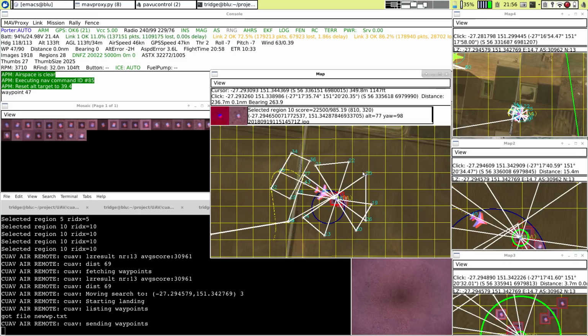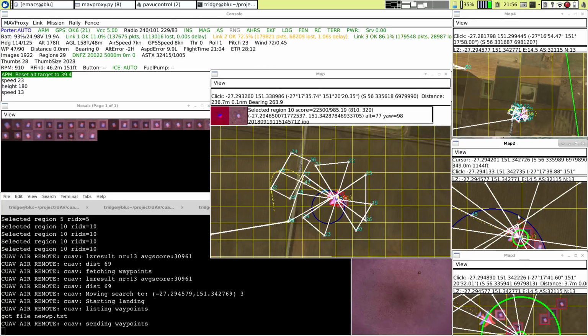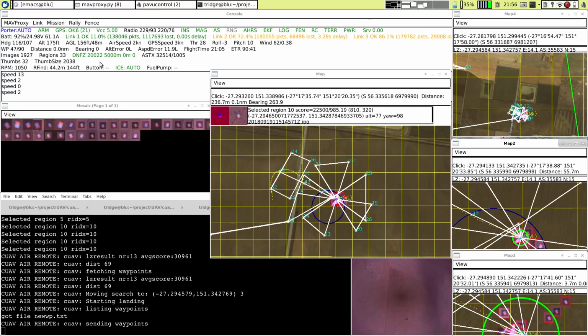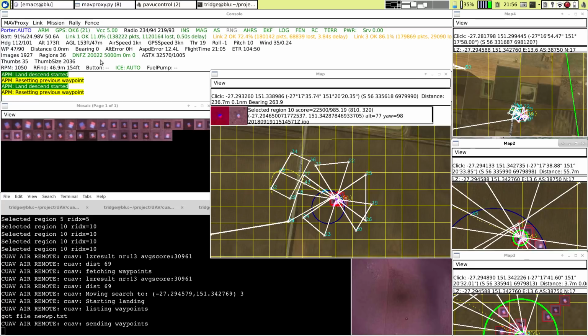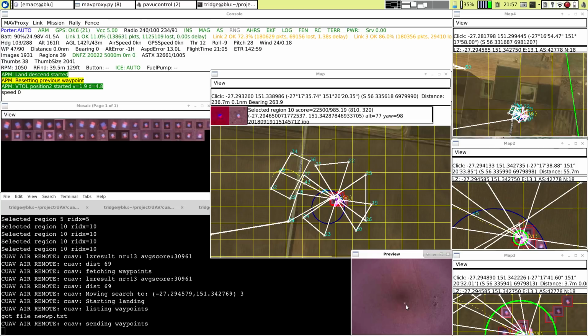So there it is, and you can now see it appearing on this map, coming in for a vertical landing. And it's slowing down, it's engaged the vertical motors, and you can see the simulated current on the motors has gone up to 60 amps, which is about the current we use for landing. You can also see it's getting lots of the target. And there's the target on this little image down here appearing in the middle. It'll get bigger as we get lower, and we can see some quite large versions of the target as we come down closer to it with these simulated images.